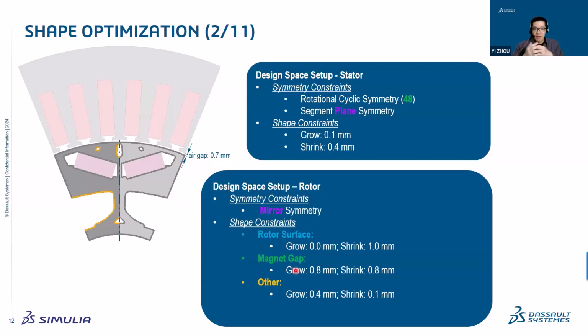So it will be fun for the optimization because it doesn't care about production. But it's not acceptable for production, because if the rotor surface and the magnetic gap approach too close to each other, we get a very thin panel. And this very thin panel will have a stress problem, and then it may tear up in the end.